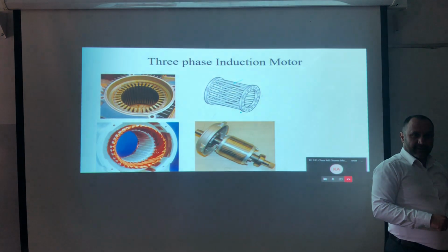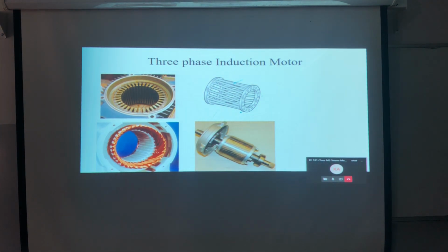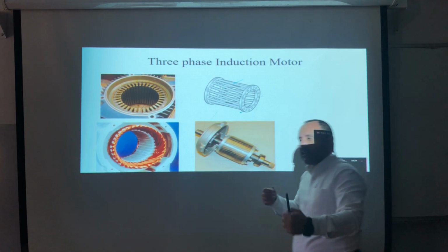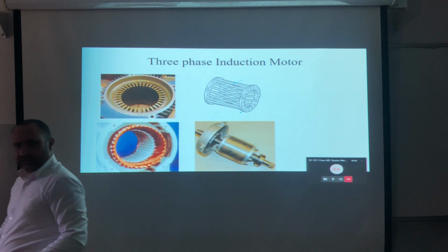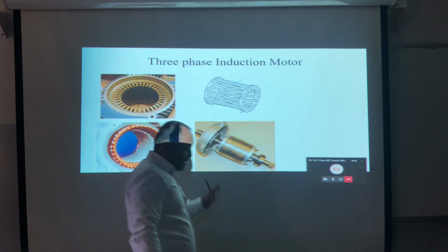No, no. You know the distance. The distance depends on what? On the angle. So this is what I'm maximizing, the distance, the length. If I'm maximizing the length, I'm changing what? The resistance. Correct? So this is a way to change the rotor resistance actually. Correct? This is the first choice.